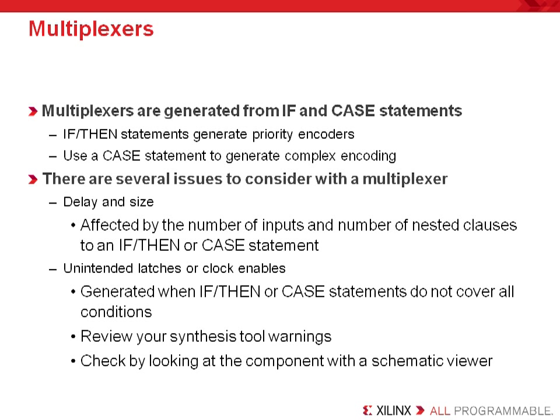You may recall that I mentioned it's important to be aware of what your synthesizer will generate depending on how you code a piece of logic. The first component we're going to look at are muxes. If you build a mux with if-then statements, synthesis tools will almost invariably build logic into priority encoders. Likewise, if you build it with a case statement, the synthesis tool does not give any signal a priority.